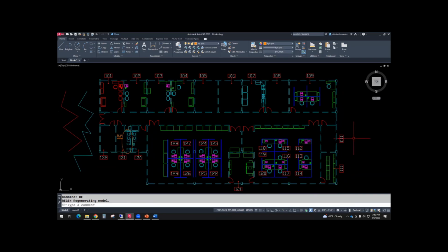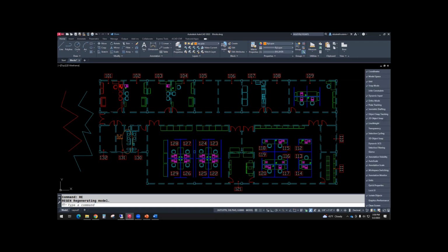And then the last thing about line types is the line weight. We had set our line weight, I think, to 0.4 millimeters, but I don't see these walls being any thicker than the other lines. If you go to your menu, bottom right corner, look for line weight. Make sure that has a check mark.